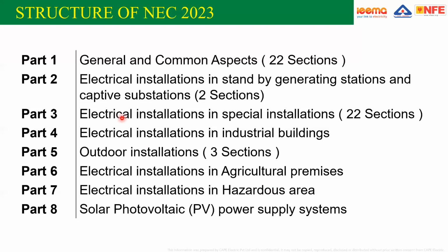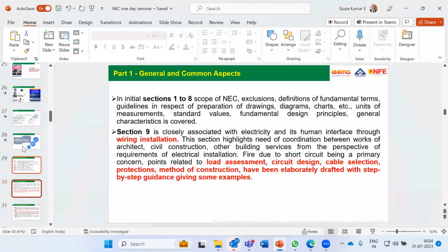My question was that now, as you have shown the slides, I could read that the Central Electricity Authority mentions the use of low smoke, low halogen, that is basically FRLS material for high-rise building above 15 meters in height. And as you rightly mentioned, it is mandatory and penalized if it is not followed.